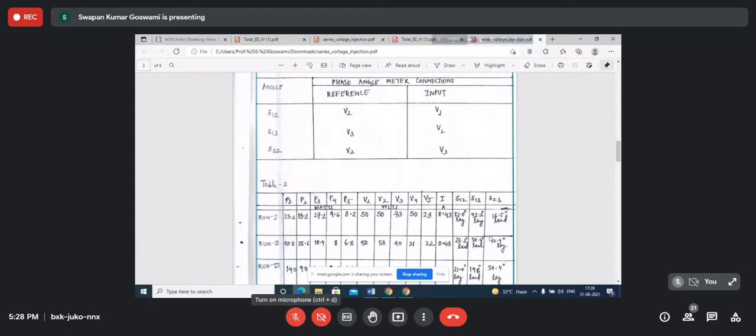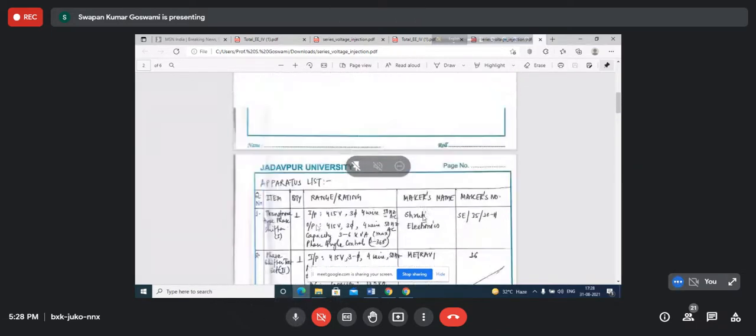Okay, but if you want to actually calculate how much voltage at what angle has to be adjusted, it is very difficult to say, because we have to, at the measurement condition, know how much current is flowing, then how much voltage and at what angle will actually push this much power. This calculation is possible, provided you can control everything. You can have the measurement of all the parameters, you have the control over all the voltages. If that can be done, that is possible. Here another thing is that the source,